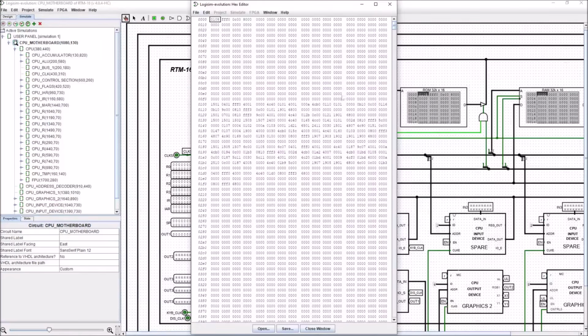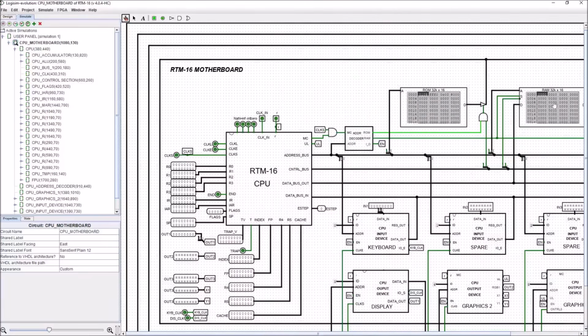Now another thing that we have to be careful of is that within these libraries we're going to have subroutines, and these subroutines are in themselves going to use temporary memory locations. So the temporary memory locations these subroutines use aren't going to be in the ROM here, they're actually going to be in the RAM.